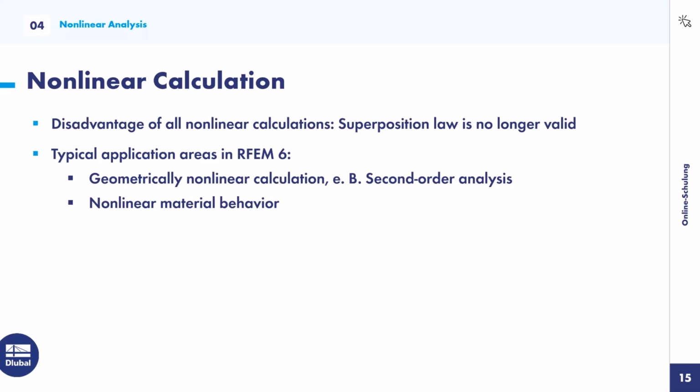Now you also take a live load case, where you have the material at 100 Newton per square millimeter. If you superpose them, you would have 335 Newton per square millimeter. The material can't do it. So it's a wrong calculation. That's just one example why superposition mustn't be used for this.